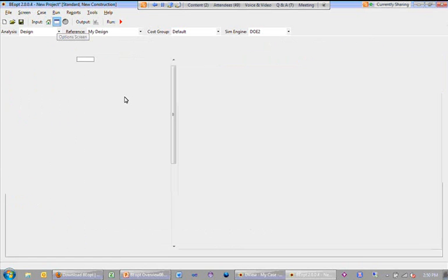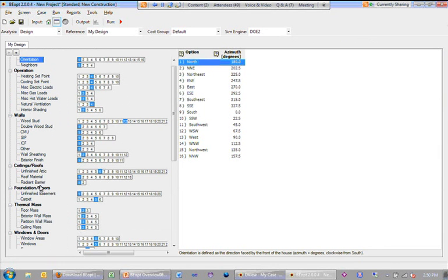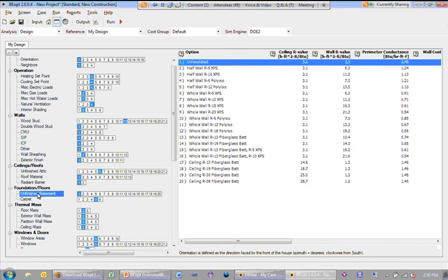Okay. Yeah, I just saw that, and I'm working on something that's supposed to be closer to kind of passive house, so definitely slab insulation. Yeah, and passive house had motivated us to do more aggressive under slab insulation, but I don't think we have an under the basement floor insulation option.